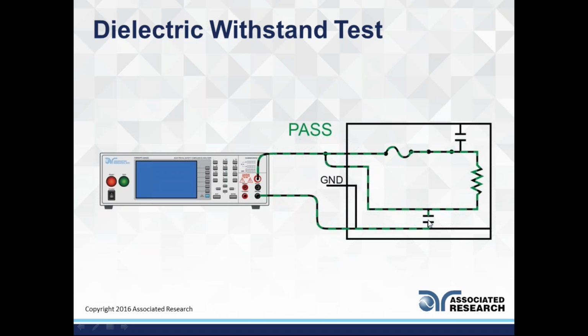Capacitor, the space here being your insulation. So right now my electric field is there and is being applied to your DUT, but your insulation is holding up. It doesn't matter how strong that electric field is, no electrons are breaking through or no current is leaking through your insulation. So that's good insulation, that's a good pass.